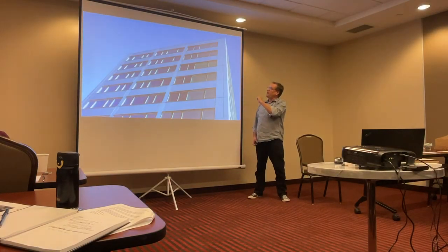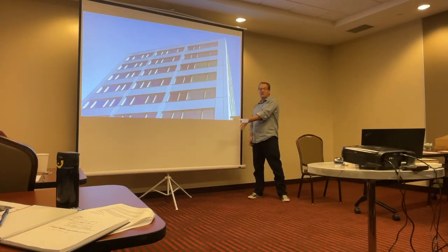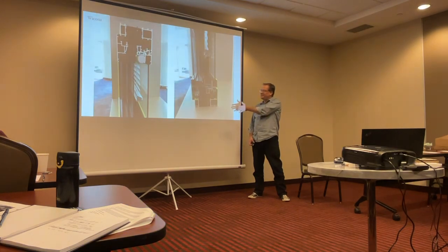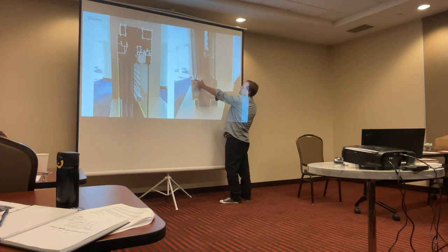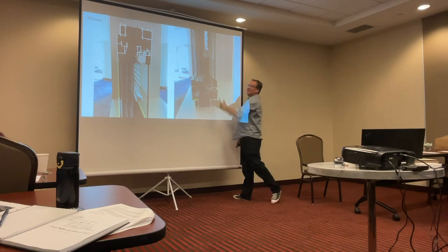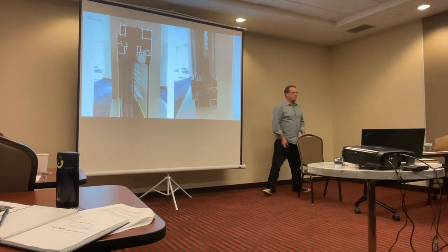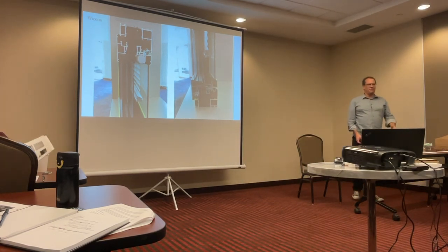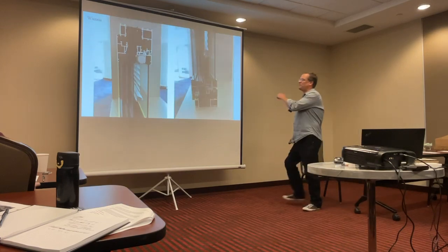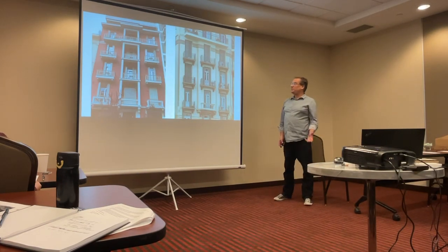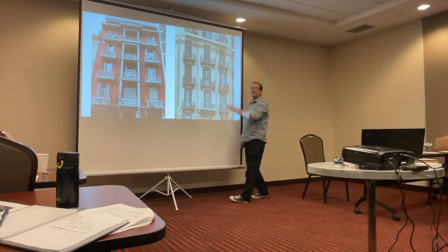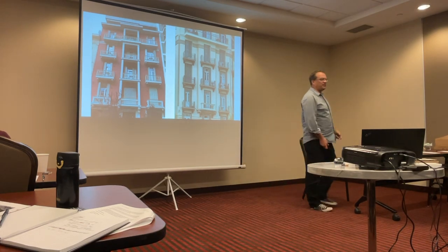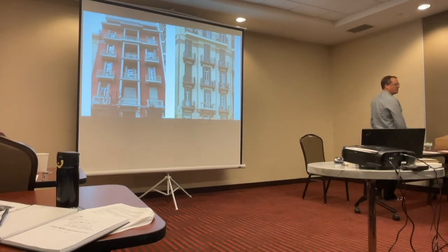really easy to move. Maybe you saw a conventional glass facade, and the shading is actually inside the window. So you've got a triple-pane window, a ventilated cavity, and the shading is in there, and it can open up. A little more money, but if you're looking for a certain kind of building, with great resiliency, it's a fantastic option, and all the big window companies make this now. Maybe you saw something really traditional. You saw shutters on the outside and curtains on the inside.